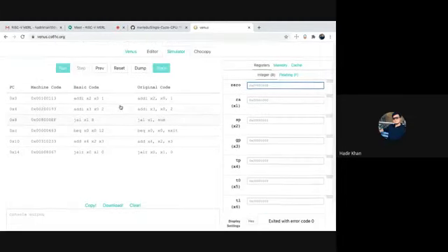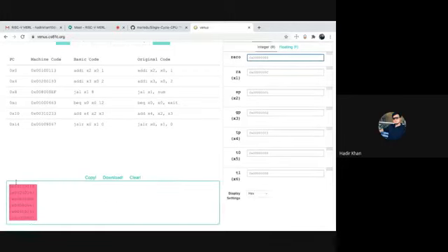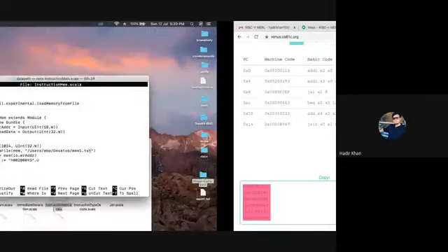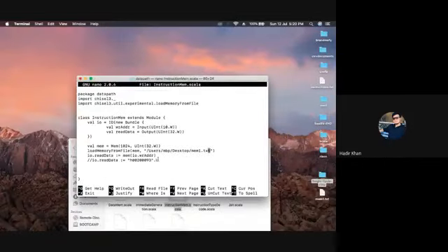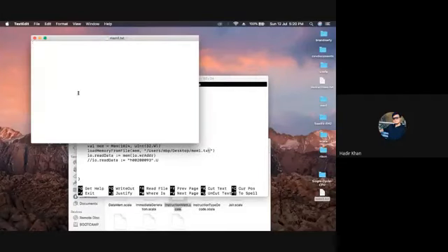Let's generate the hex file of it. So I'll press the dump button here, and this generates the whole hex file of this program. I'll copy it, and then I'll come here. Okay, so right now my file is present on the desktop with mem1.txt, which is this file right here. So I'll open it, and I'll paste the code here and remove these 0x's. All right, because then it'll give you error if you don't remove it. 0x just represents hexadecimal notation, so we don't need it here.